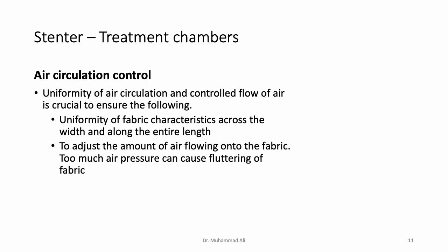if the air is blown with too much pressure on a low GSM lightweight fabric, then this can cause excessive fluttering of the fabric. And this is not what we want, because excessive fluttering of the fabric can result in the fabric getting detached from the chains, or other damages to the fabric can be caused.